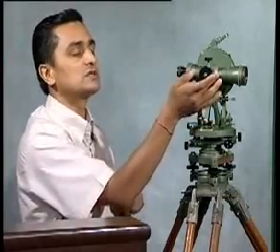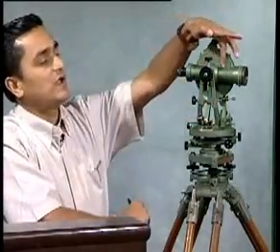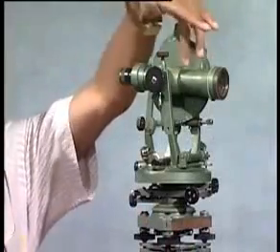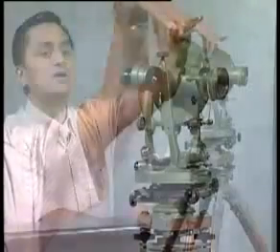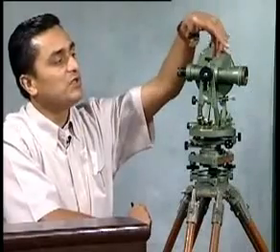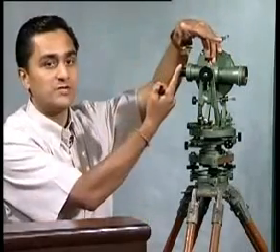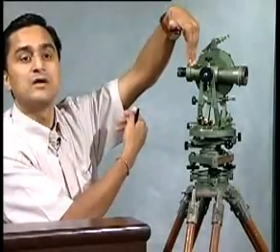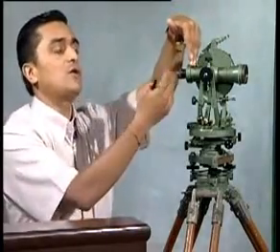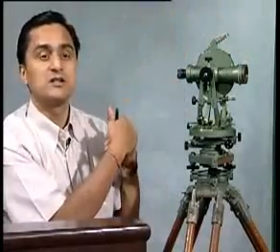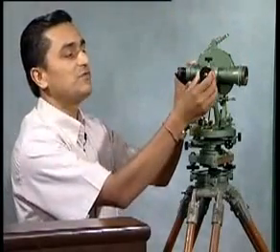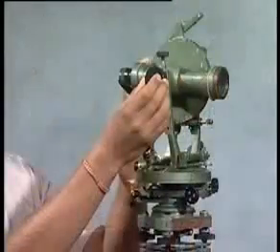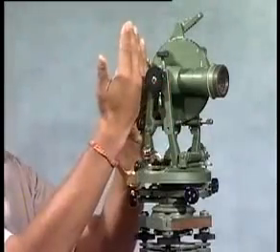So when I am using it, what is happening? There inside the telescope, an extra lens is moving here inside, so that it is ensuring the image which is being formed inside this telescope of the object will finally form on the plane of the crosswire. Because I can see the crosswire distinctly, I will also see the image of the object distinctly now. So this is what is achieved by focusing the objective. That image is formed here in the plane of the crosswire. So I will start seeing now the image very, very distinctly, no fuzziness in that.